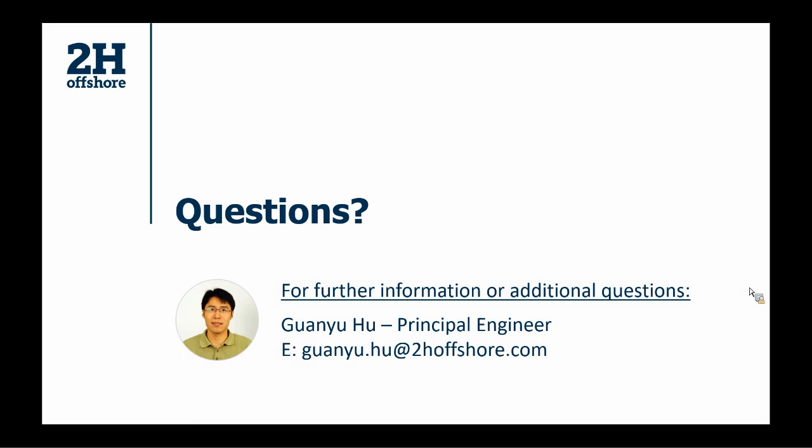Okay. The next question is, are there any recommendations on what we should be doing for life extension assessments? Yeah, that's a good question. For life extension, we recommend to use the hysteretic model for fatigue analysis. That way, if, for example, the original design was based on fixed stiffness, which means there is a large conservatism in the design, then using this new method will remove a significant level of this conservatisms.